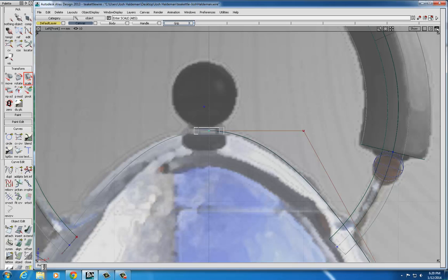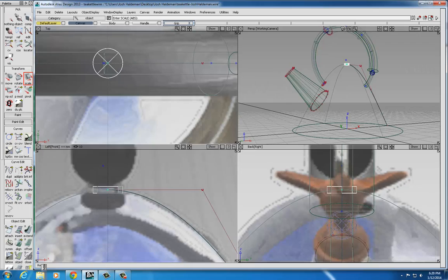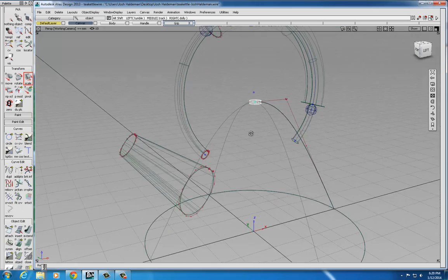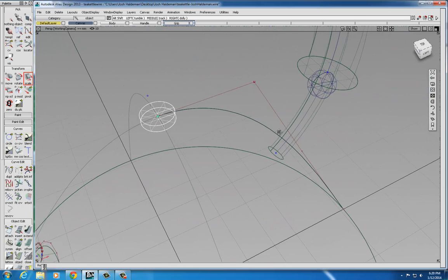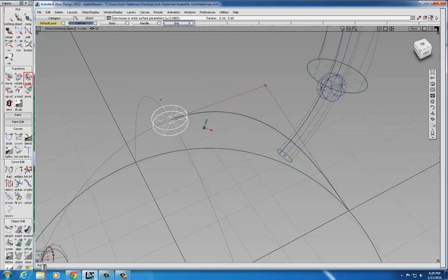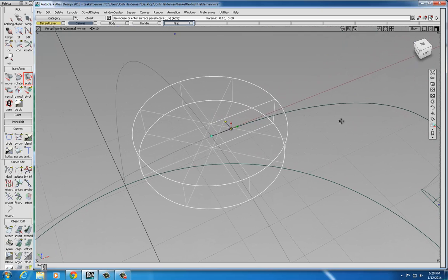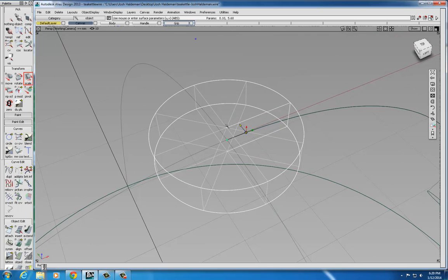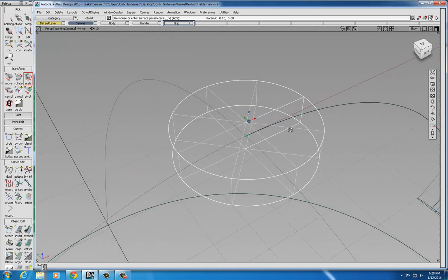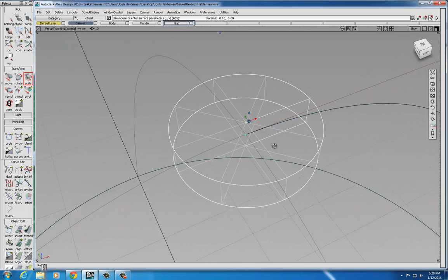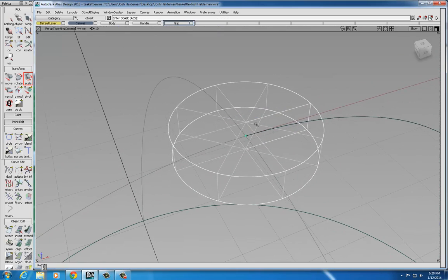Now I want to place my sphere for the top, and you know what? The method we use to create the grip decoration is also the appropriate method for creating the knob in the center of the lid. So I'm going to go to my perspective window to get started here. Scroll up so I can see the top of that lid. And if you're having trouble getting your camera to zoom to the right place, make sure that you hold down Shift Alt and pick a point in your scene. Then when you move your left mouse button to tumble around your view, it'll rotate around that new pivot point.